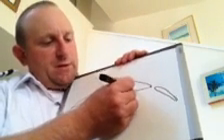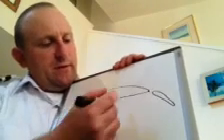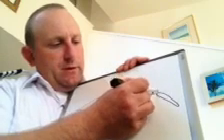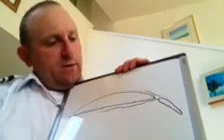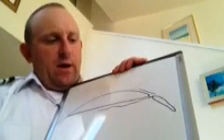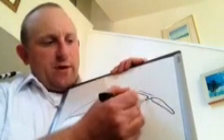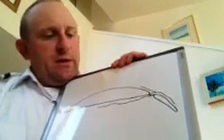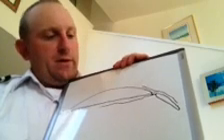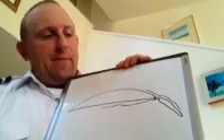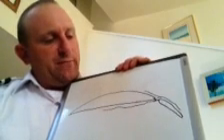The good thing about this airflow is that the airflow that comes under the wing is allowed to join the airflow from the upper surface of the wing, and it's high velocity airflow, and it delays the separation of the airflow from the boundary layer, resulting in more lift. So there's not an early separation when they join together. That high velocity air keeps that airflow over this increased cambered surface for a longer period of time. So that's one of the significant advantages to this type of flap, the slotted flap.